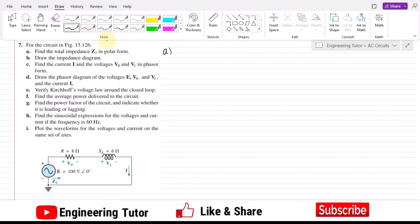So in part A, ZT is equal to the total resistance. The only resistance we have is this R, and similarly here we have the inductor, so it has the inductive reactance, with which I have to write plus j, so it will be plus jXL. Okay, so now writing their values, it will be 8 plus j6. So this is now in rectangular form.